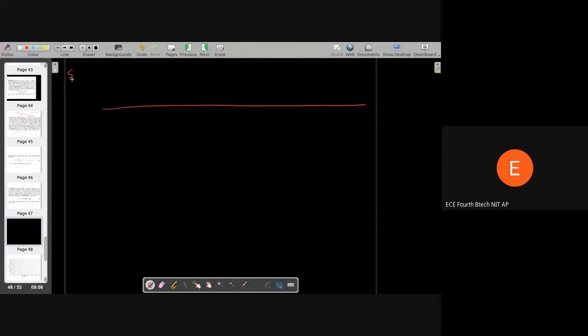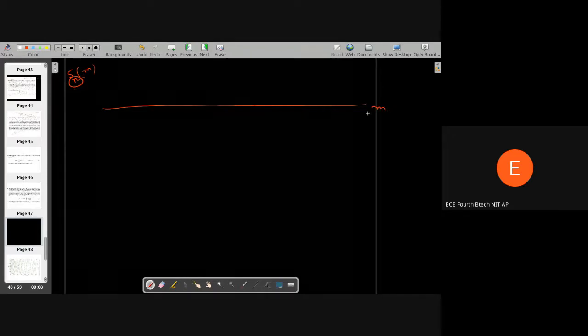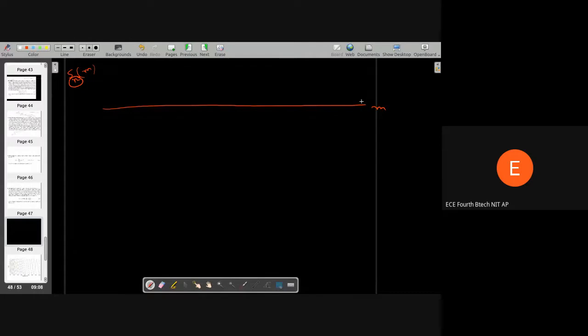After windowing, this is our signal windowed at a particular point n, and I am taking the index as m, the time domain index. Whatever the signal comes in that, this is your center, and whatever the speech signal looks like in that window. Now from that we have S_n(e^{jω}), but instead of just taking magnitude, we will take magnitude square.